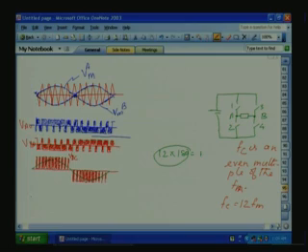If you see the FFT spectrum for this one, we can draw it. You have the fundamental, then the harmonics at FC will not be there, they will be highly suppressed, and the next harmonics happen only at the sidebands of 2FC.